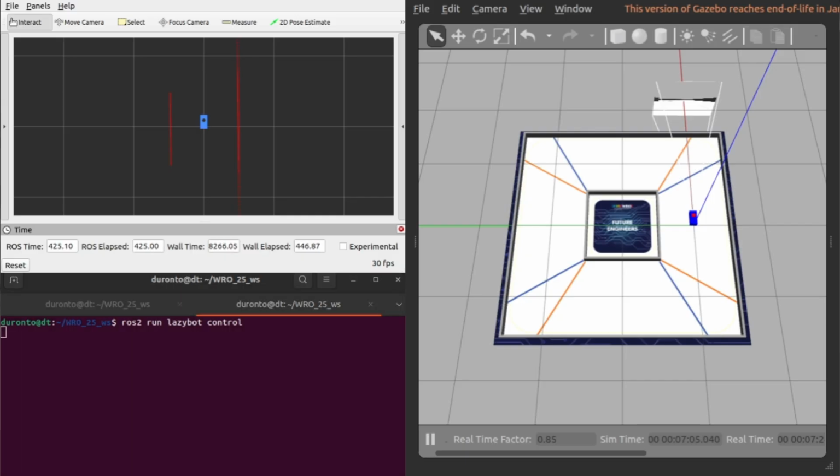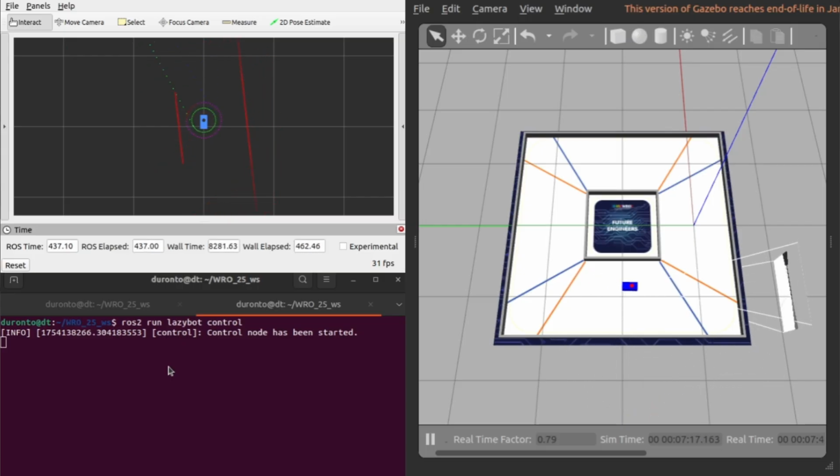So what I did during that time was set up a simulated world in Gazebo. By the way, Gazebo is a robot simulator. If you have a 3D representation of your robot, then you can simulate it there. Fortunately, Gazebo has really good compatibility with ROS2, and I did all my logics on the simulated robot, and when I came back to my team, I implemented those logics on our actual physical robot, and it worked just fine. All the simulated files and necessary scripts can be found in our GitHub repository.